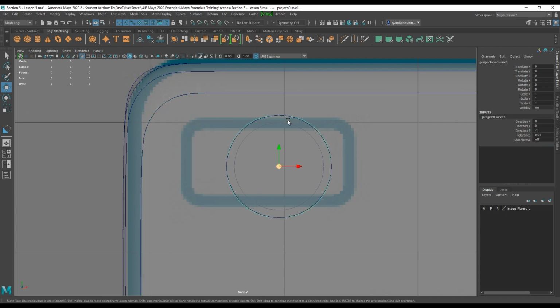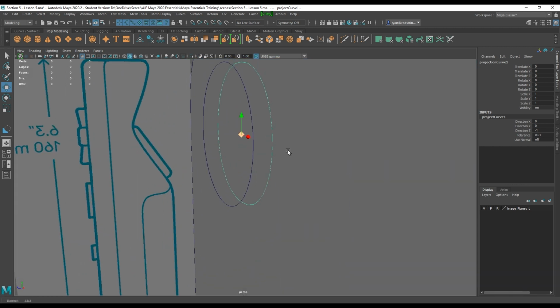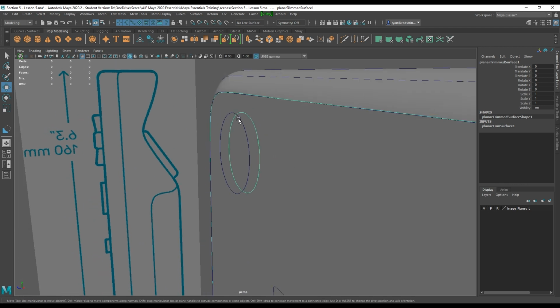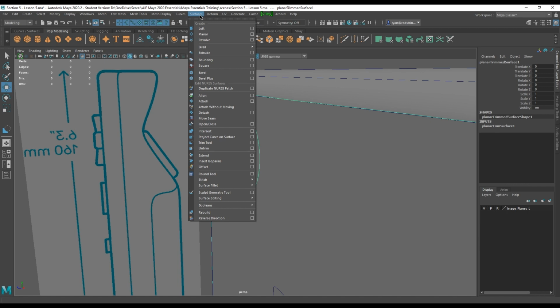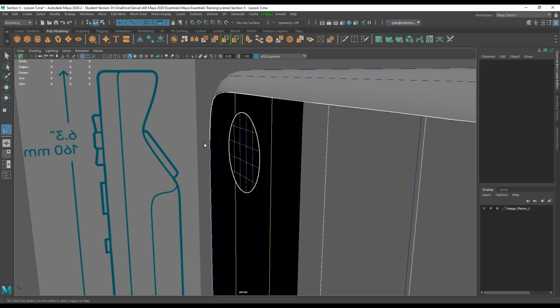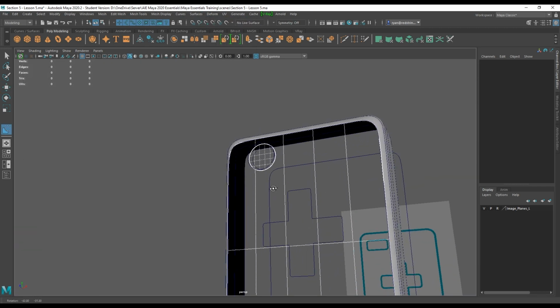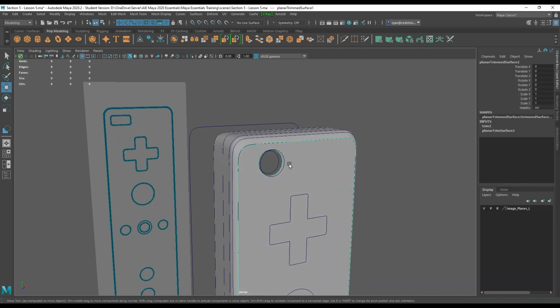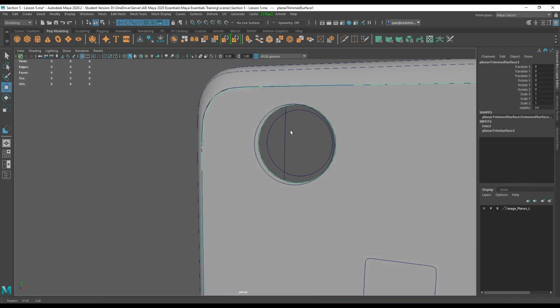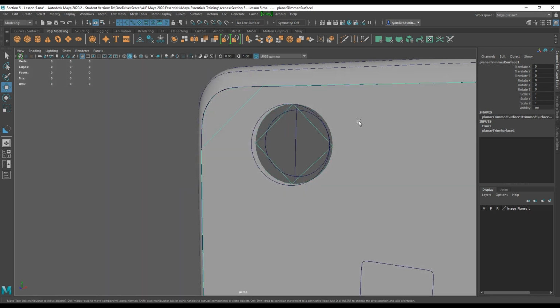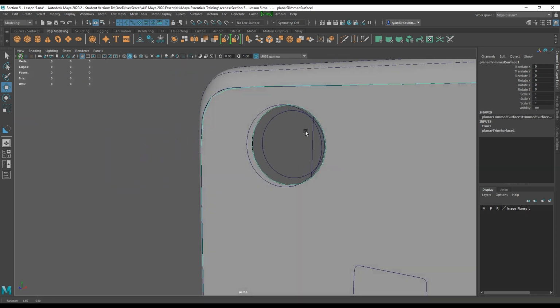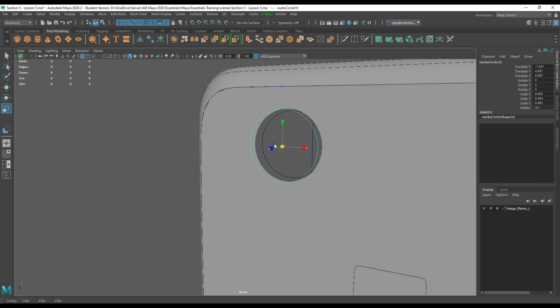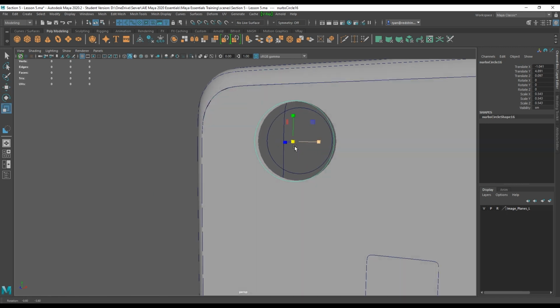That's pretty low res. So I'm just going to press 3 to smooth it out, because even NURBS surfaces are finicky like that. Now that curve is on that surface. So if I select a surface, you see it highlight. I'm going to go to surfaces and use the trim tool, and then I click on what I want to keep. So this big guy I want to keep, and then press enter, and it doesn't really throw away, it theoretically hides that surface in there for us, which is very cool, because there's also now the history that we can have, and we can scale it up as we need it.